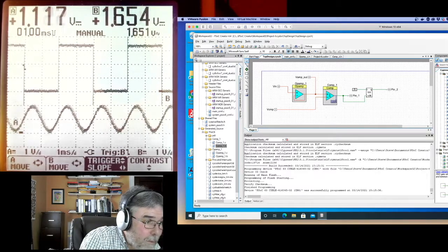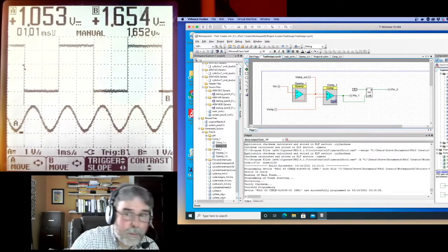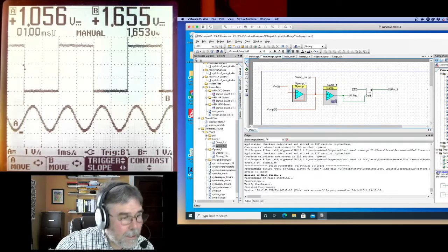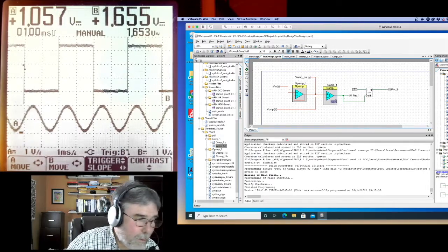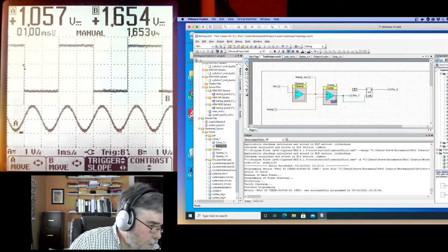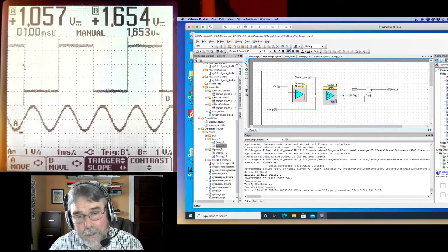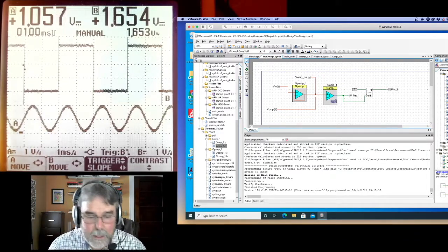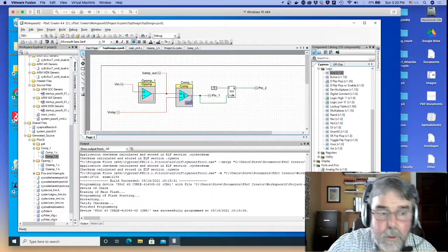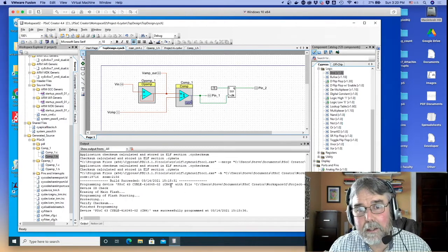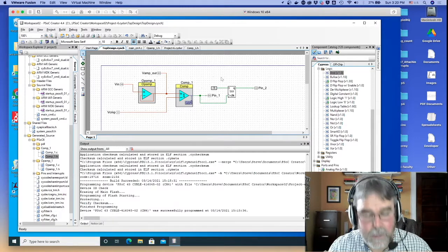But if I move down to the output of that flip-flop, and then I change the sine up and down, it doesn't do anything. And the reason is, of course, the flip-flop doesn't care what the duty cycle of the output of the comparator is. It only cares how often it ticks. And how often it ticks just depends on the frequency of the sinusoid. It doesn't depend on the level or the threshold or any of that stuff. So, okay, that's the main idea. So from here on, you guys just need to add 2 more flip-flops and that AND gate to match the original circuit.